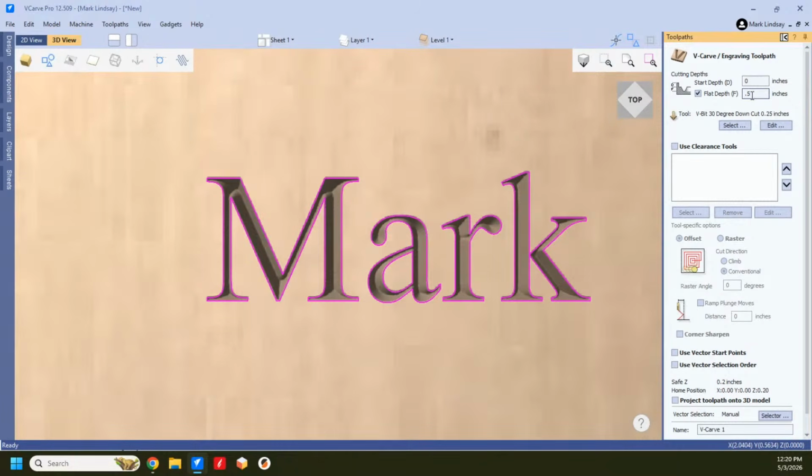It won't cut any deeper than a 1/2 inch. So, using 0.25, that's a limit. It won't cut any deeper than a 1/4 inch. So all these areas out here that are deeper than a 1/4 inch are not going to have this pointed bottom, this angled bottom. They're going to have a flat bottom.